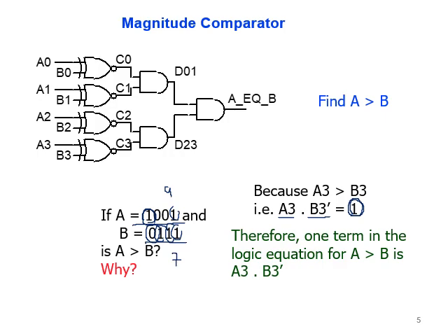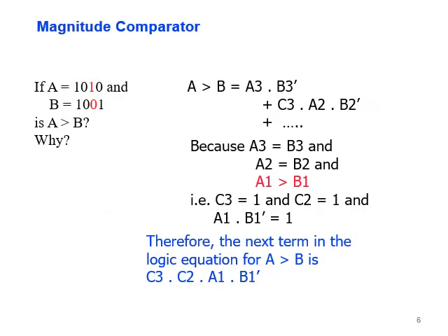Now, this is not what always happens. What if, in the previous example, we directly compared the last number to the left, done. But here in this example, you see 1 here is equal to 1 here. So I go to the next weight or next order bit. 0 is equal to 0. But 1 here in red is not equal to 0. You got it? So A greater than B.